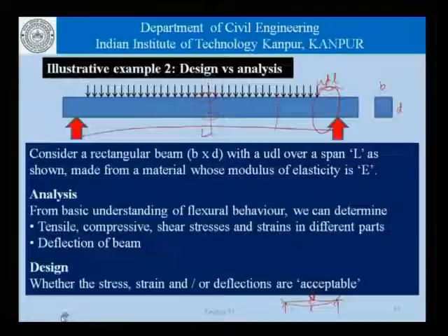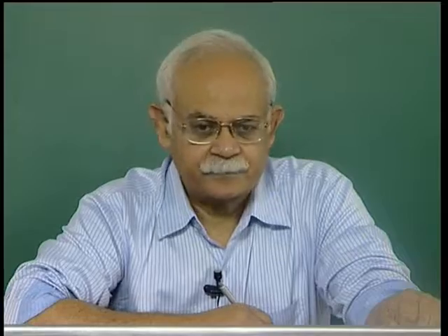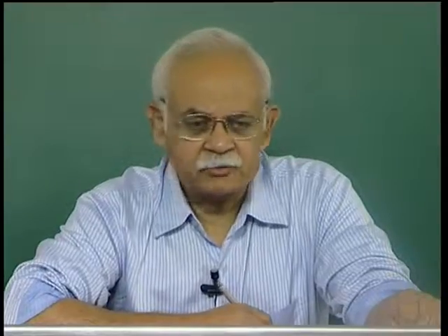We have specifications which tell us that the deflection of a simply supported beam, which is maximum, let us say, at the midspan, should not exceed L/325 or L/450 and so on. Where those numbers come from is a different story, but it is important to understand that the designer needs to satisfy the criteria that are laid down in the design specifications.